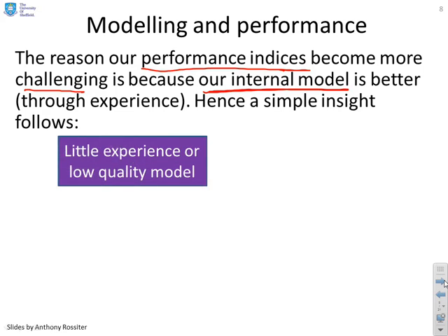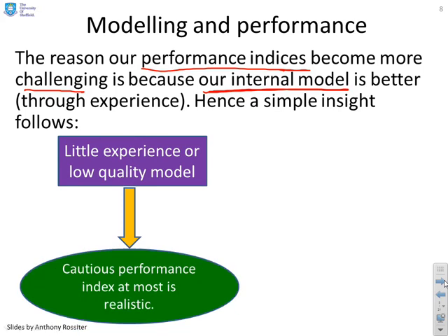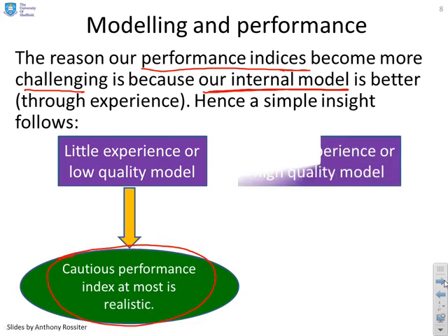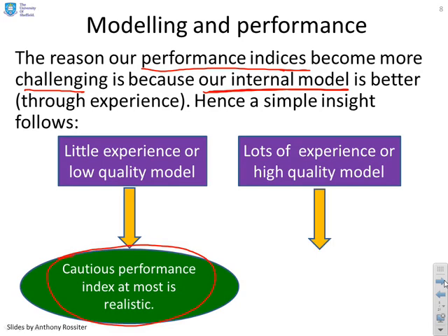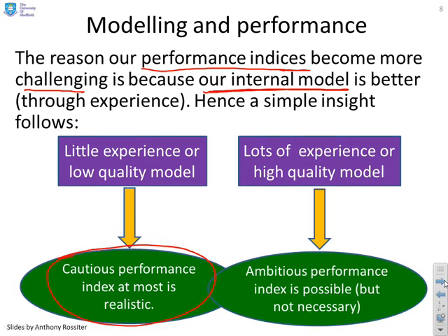If you've got little experience, or equivalently a low quality model, then all you can expect is cautious performance. So your performance indices have to be fairly simplistic and not asking a lot. Conversely, if you've got lots of experience, or equivalently a very high quality model, then you can have very ambitious performance indices.